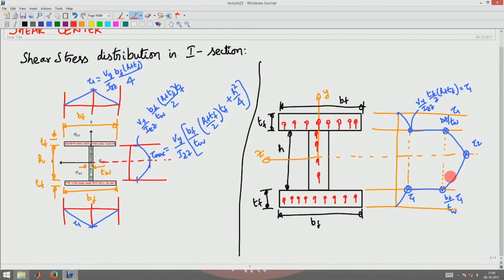Also we saw that depending upon how the section is built up, whether the sigma xz shear is going to be resisted by the nails or weld, or sigma xy stress is going to be resisted by the nails or the weld, you have to use the appropriate shear stress distribution to compute the connection shear stresses, and then do the connection detailing. In the last class we also alluded to the possibility of a torsional moment arising because of this shear stress distribution. In an I section there won't be a torsional moment because the moments are balanced, because the flanges are of equal width in both directions.